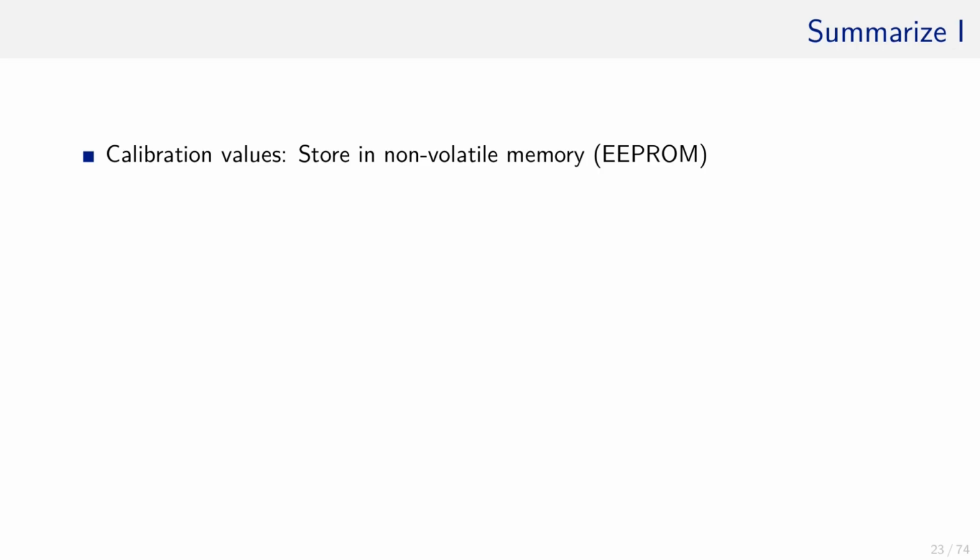A more convenient method would be to upload your program and execute it in a calibrated environment of, for instance, 25 degrees Celsius. When the program is started the very first time, both T off and K values are computed and stored in non-volatile memory.